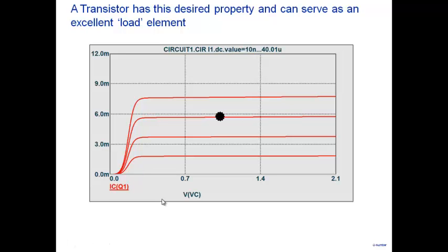Look at it. Say I have a transistor and I bias it somewhere here. If I bias my transistor here, can you see where the DC drop is? How much is the DC drop? Look at that here. 1 volt or so. I bias it here. What is the small signal resistance at this particular point? The small signal resistance means the slope. The slope of this particular line is practically 0 or very small, which means that the resistance is very high.